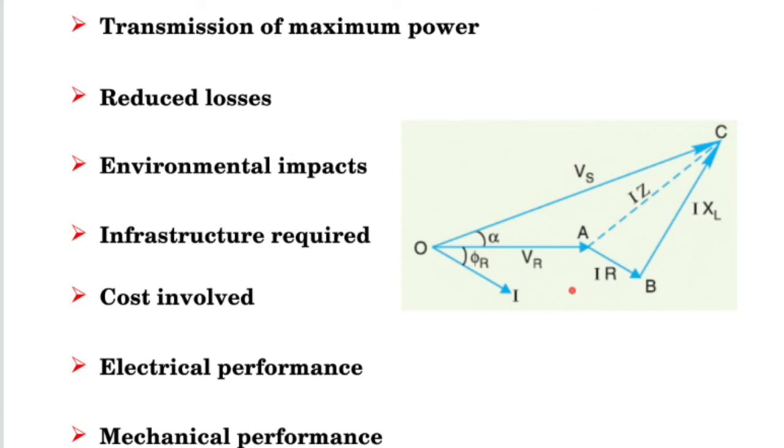After the generating station, what do we have? We have the transmission line, and due to magnetic flux, inductance, they will draw some reactive power. So they have lagging reactive power. Is it possible to have a condition that the generators at the generating stations are running at unity power factor? There is nothing else connected to the generator other than the transmission line.